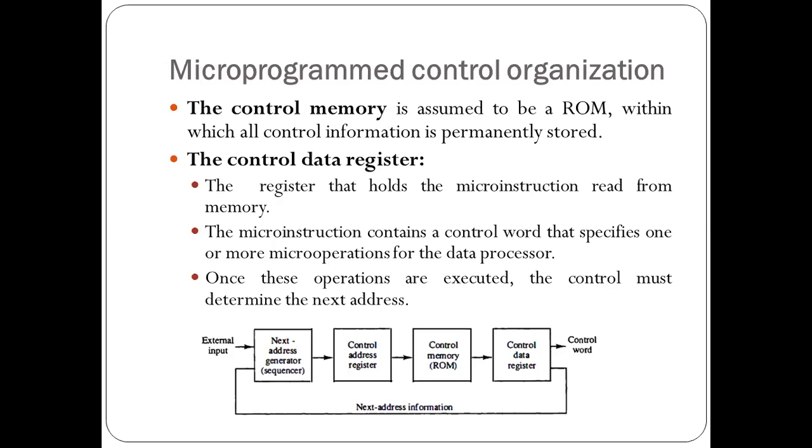Basically, the control variables at any given time represent a series of ones or zeros, that we call a control word. Okay, your control unit, which has all these control variables, which are binary in nature, can be set or reset. They are stored in your memory, which we call the control memory. And that is said to be the microprogrammed control unit.